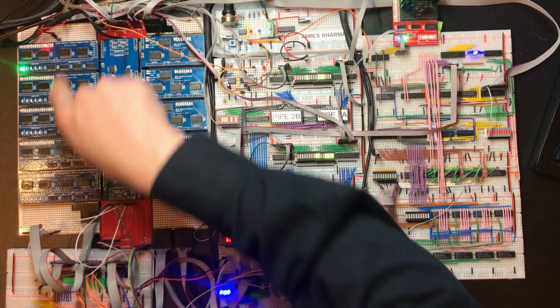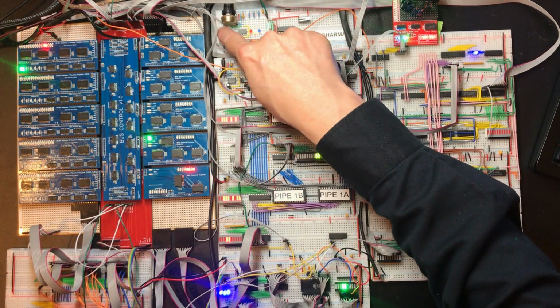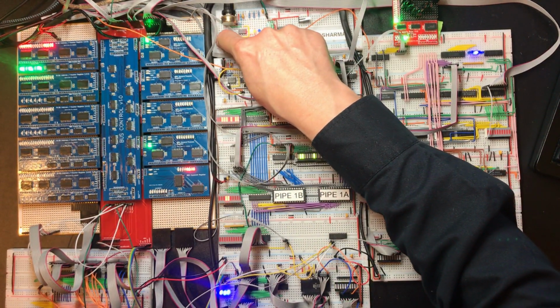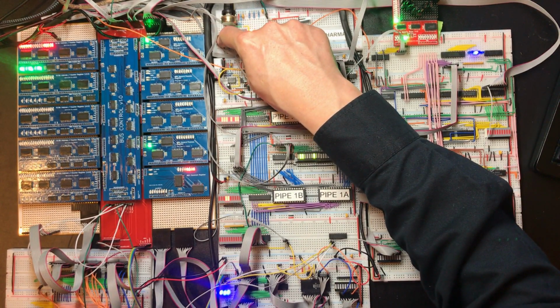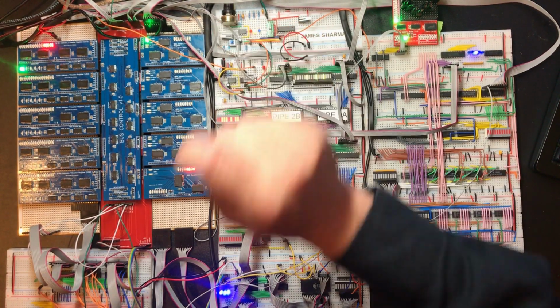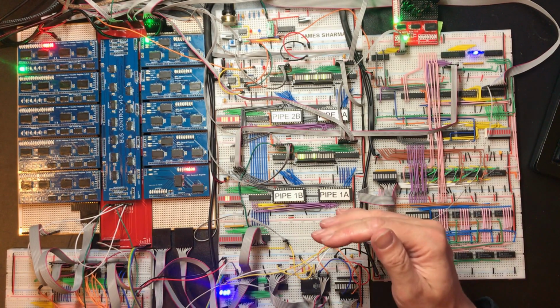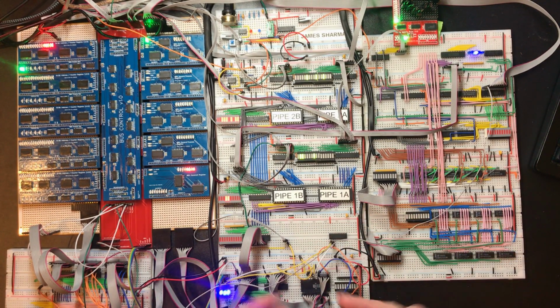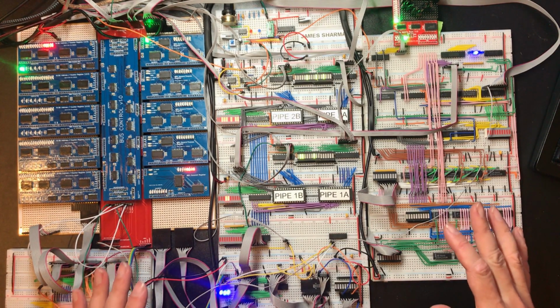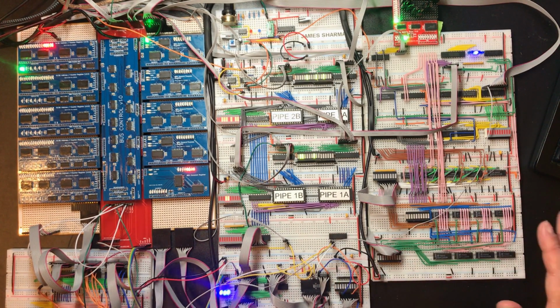So this is going to get chucked into the program counter. And there's our problem. We've got the increment happening and the increment doesn't behave properly while the load is in progress. Now those lines aren't happening at the same time, but it does switch from the load directly to the increment with no space in between. So in hindsight, I probably should have predicted that I'd have an issue with that. Let's think about what we can do about it.